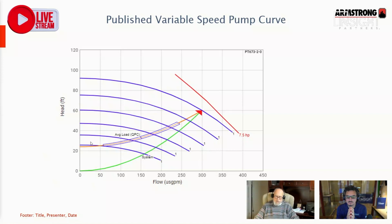If we know the system curve and the design point, and engineers tell the building automation guy to put a differential pressure transmitter out in the system and control to a set point, we know the calculated value at the pump should be about 40% of the design head.